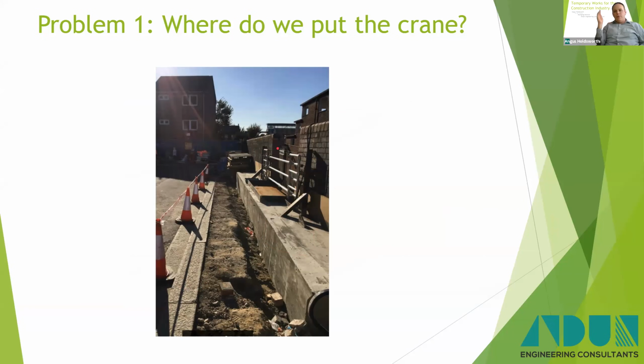Where you cut through a masonry wall and create a new end, you can artificially increase the wind loading. So as a belt and braces, we designed the system to allow us to prop the wall at the same time and give us edge protection. So that's a good example of designing out a hazard in a quite simple manner.